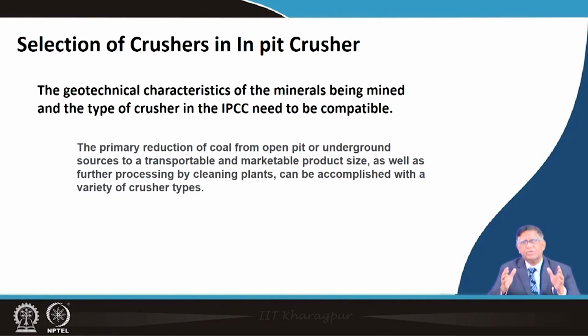Even if it is mixed, we know that the compressive strength may change from this value to that value. If it is coal, it may be even 40 megapascal or sometimes 80 megapascal, so wide changes are there. Another thing is that the rock mass may have different abrasivity.